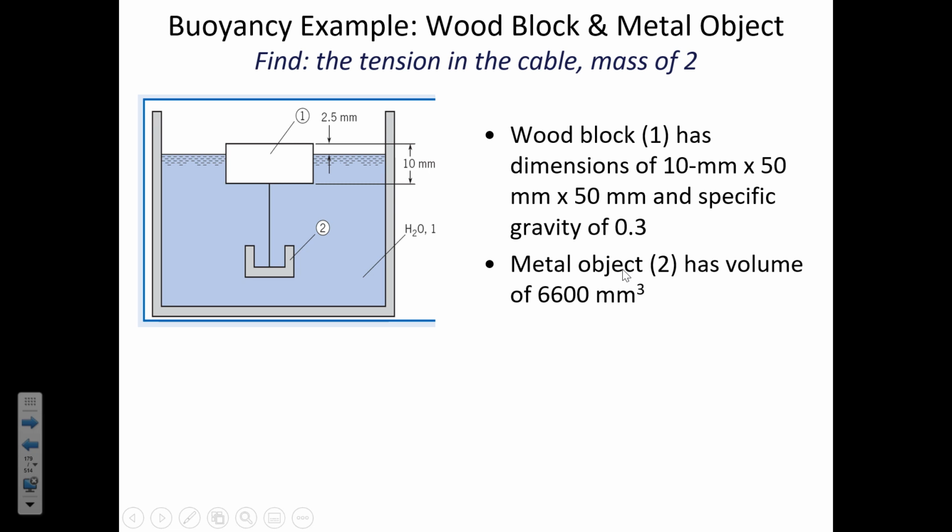Sometimes I see people accidentally saying, well, then that must mean that this is 6.6 cubic meters. But it's not. If it's 1,000 millimeters, that's just the 1D dimension conversion. If you want to convert from millimeters cubed into meters cubed, you have to cube this. So it's 1,000 millimeters by 1,000 millimeters by 1,000 millimeters. So how many millimeters cubed are in 1 cubic meter is 1,000 times 1,000 times 1,000. So you can do that now. Multiply it together. 10 to the 9th.